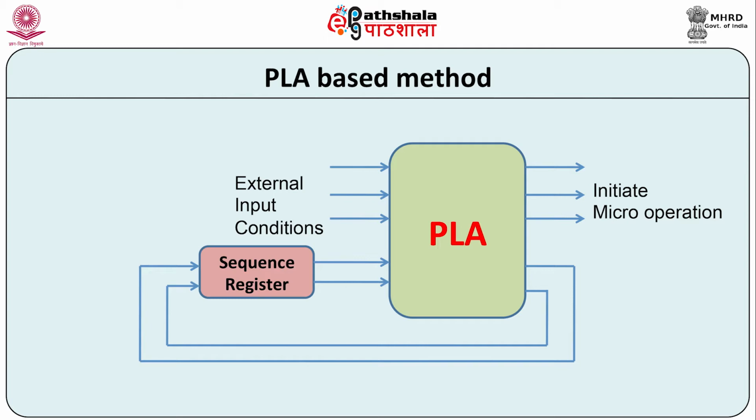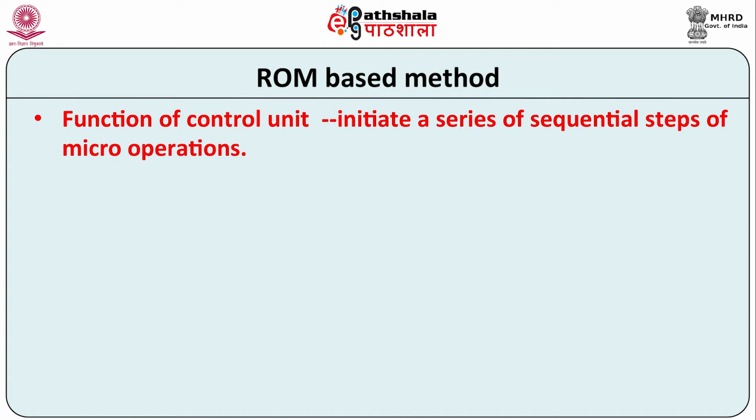The PLA outputs are also fed back to the sequence register to decide the next state. In advanced PLA, the device includes not only combinational blocks, but also some flip-flops within the unit. Such PLA provide single chip solution for control unit design. Finally, now let us discuss the ROM based method for designing the control unit.